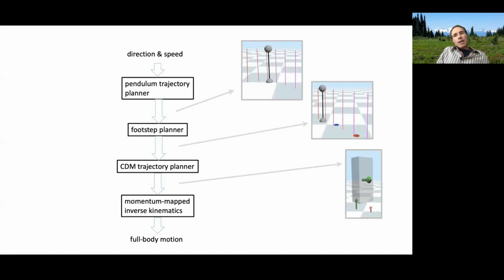And then the next level is to move away from the inverted pendulum on a cart and towards the centroidal mass model. At this point, we consider the body, the classic potato model, where the dynamics is simply modeled by the center of mass and also the angular position of the body, as well as the linear velocity and angular velocity of the body. With this single rigid body abstracted dynamics, our goal will be in part to compute the ground reaction forces over time to make this center of mass model actually follow the center of mass trajectory that we want to see over here, that was computed for the earlier inverted pendulum model. So this is adding on additional detail.